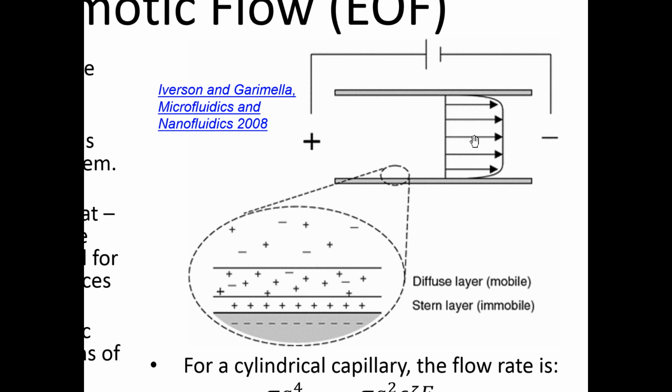So you can see this is a very different philosophy on pumping than the conventional way of thinking, where you have a peristaltic pump or your diaphragm moving back and forth. In this case, you're actually using electric fields. The ions within the liquid are charged, and you're putting an electric field to move those ions, and when those ions move, they drag some liquid with it.